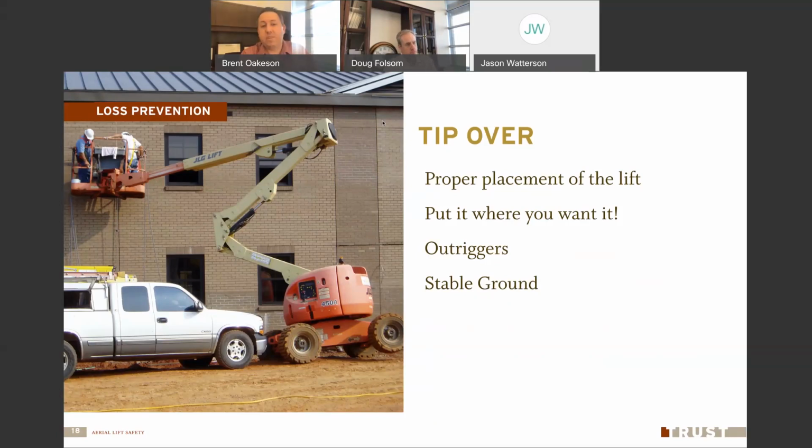If your equipment comes with outriggers, you're supposed to use those. Make sure you put the outriggers down, wheel chocks, or anything that you're supposed to do per the manufacturer to make sure that thing is stable. Also check the ground that you're setting up on. Make sure that it's level, that it can support the lift, that it's in good condition, and it's good and safe to go up vertically before you put yourself at risk there.